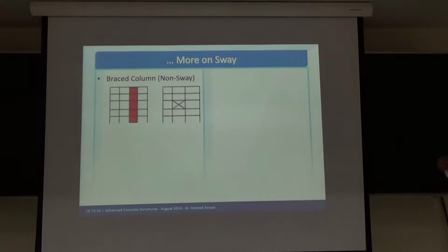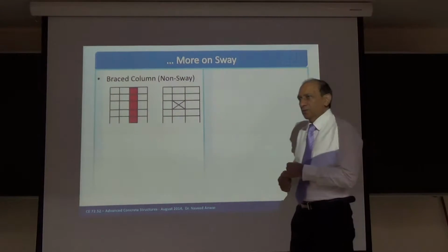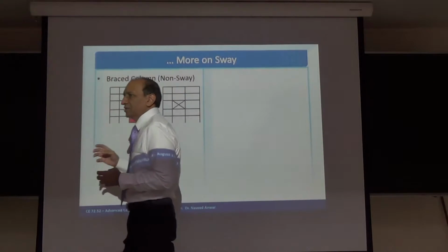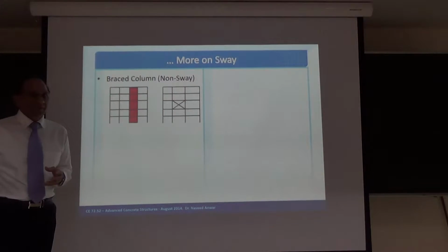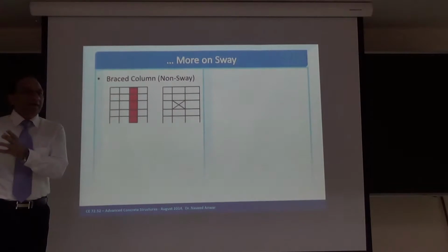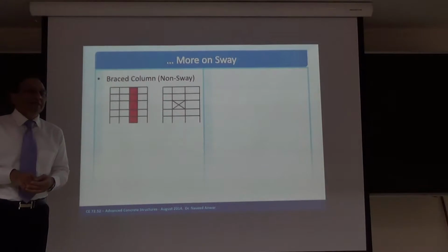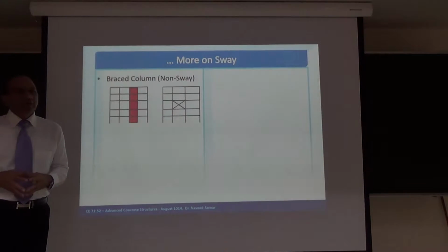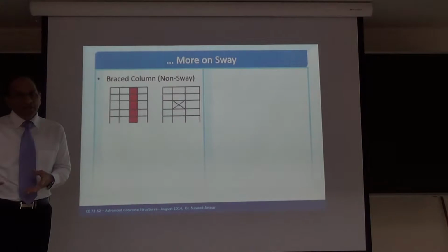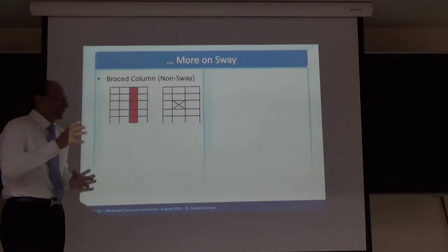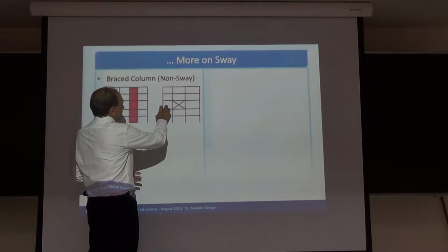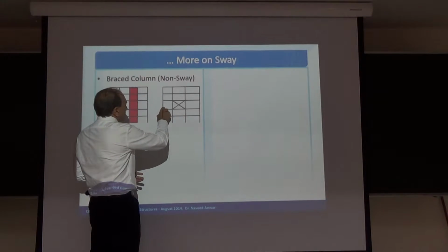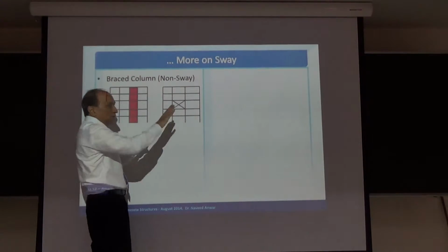As I mentioned to you, the problem is with the stiffness, because the slenderness issue is related to deflection, and deflection is related to stiffness, stiffness is related to cracking, and also related to the nonlinear stress-strain curve. So it's a very complicated problem, and it cannot be solved easily because moment magnification in one column causes moment magnification in beams also, and that spreads away.